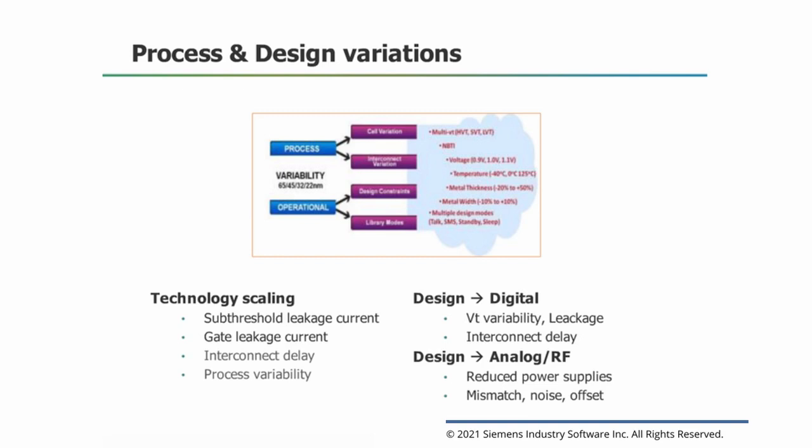For instance, leakage currents are no longer negligible. At smaller geometries, variability also gains in importance simply because the same absolute tolerance becomes relatively larger when the absolute value of parameters decreases. For instance, a variation of the threshold voltage of 50 mV relative to a VTH of 200 mV is a much bigger problem than relative to a VTH of 700 mV.